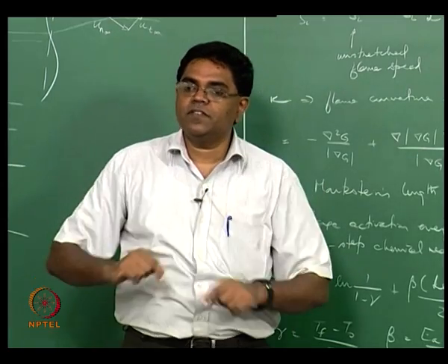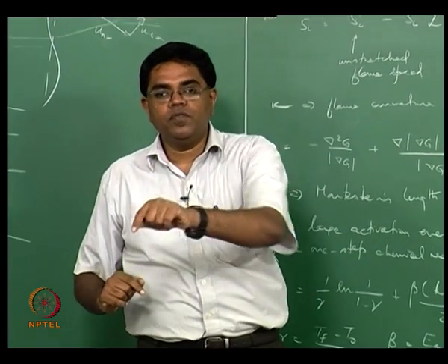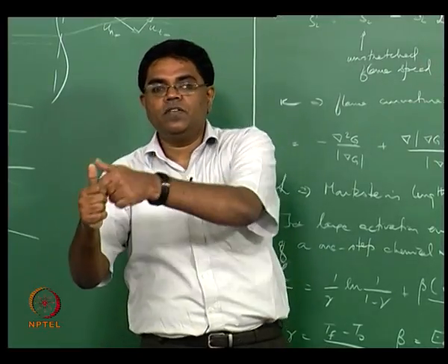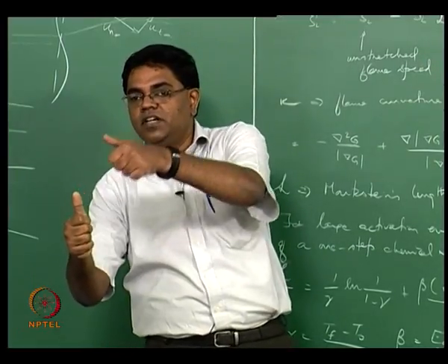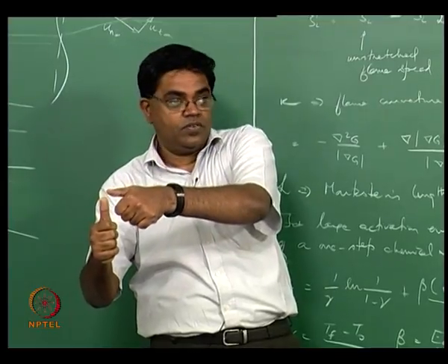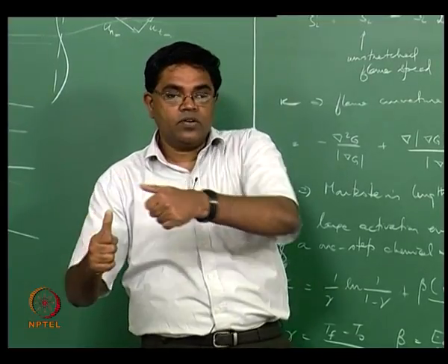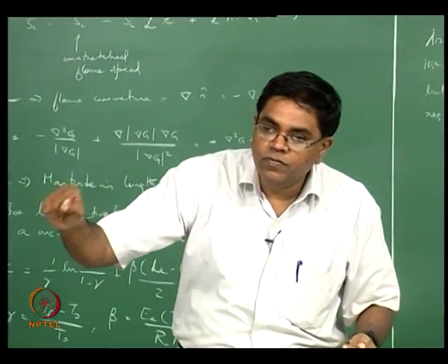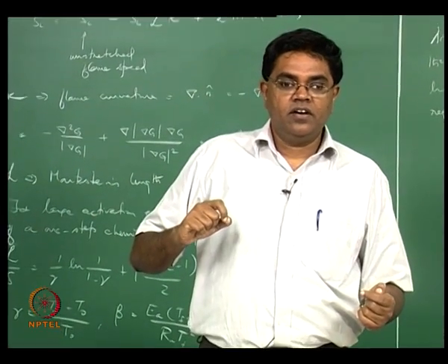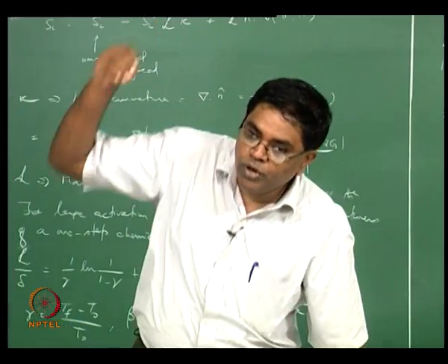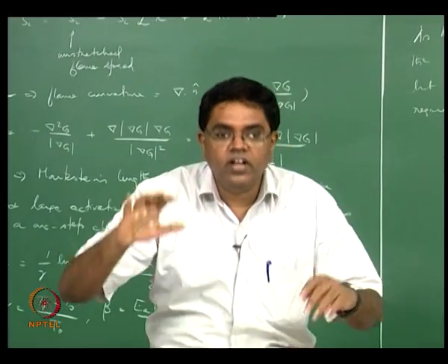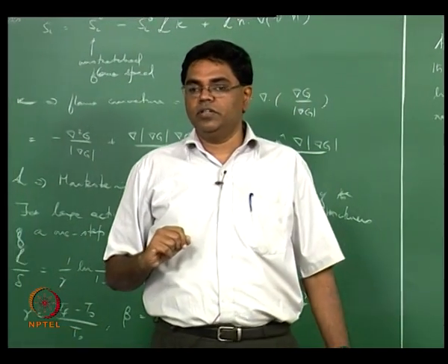But that was not the case for the flow as well. The flow wasn't uniform there. It is coming out of a burner and it has to satisfy the no slip boundary condition. That means the flow velocity has to start from 0. So we begin to think, wait a minute, if you're going to have a 0 flow velocity there, that means the flame should be able to propagate against the flow right there along the walls and never really be stabilized above the burner.